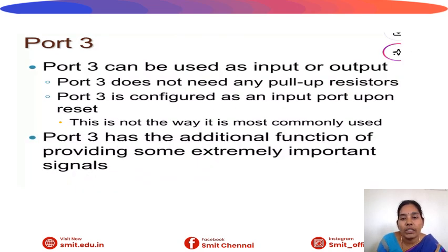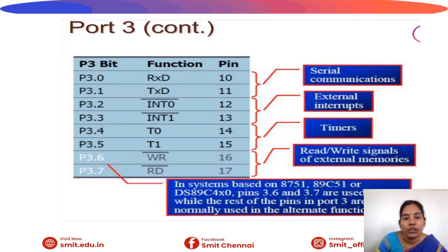Port 3 pins are used as input-output ports. In addition, the functions of the port can be used for serial communication. The functions are transmitting the data and receiving the data. You can use port 3 as external interrupts. These functions are interrupt 0 and interrupt 1. You can also use timers on port 3, timer 0 and timer 1. You can use read and write signals for the external memories.